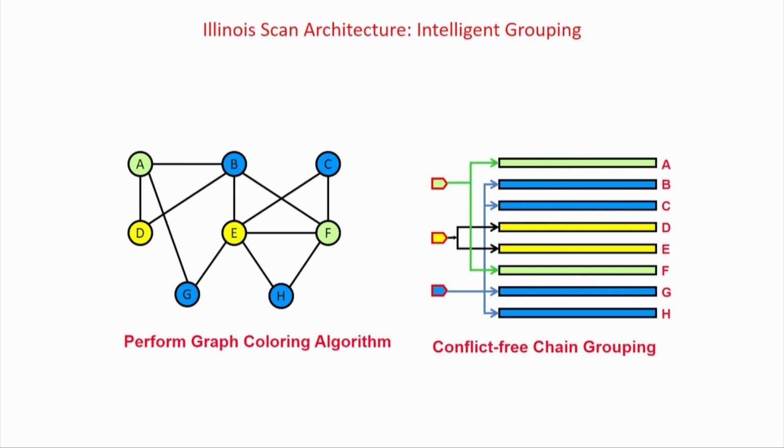So therefore, a lot of research has been devoted to finding out how we can optimize scan chains as well as reduce the test application time and not make any test faults untestable. The Illinois scan architecture is one of the most prominent architectures for that, which we have mainly discussed in this lecture, along with partial scan. Apart from that, before I finish the lecture, other types of scans have also been proposed.